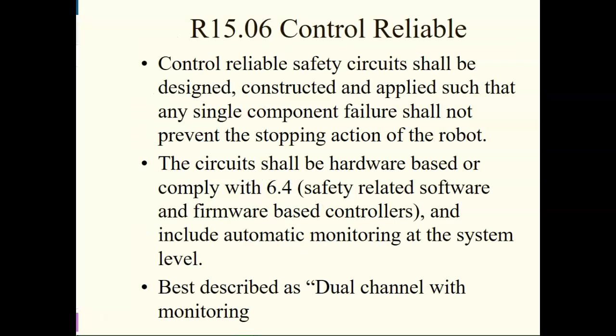So one of the things we have to do when it comes to safety equipment is create redundancy. Why is redundancy a good thing? First one fails, you want a backup. That is absolutely true. You want any way to stop the robot to be control reliable, because if it's not, and one component fails to trigger, you're done.